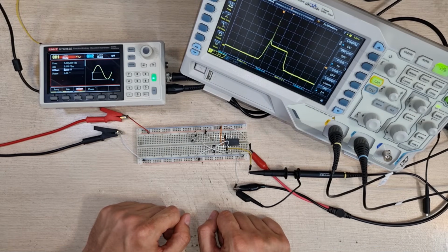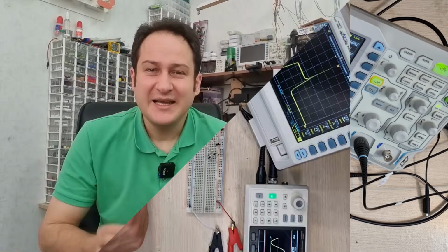If you refuse to use this diode here, the microcontroller in your circuit will reset every time the relay switches off. It is not just relays. All types of inductive loads make spikes, like DC motors, buzzers, solenoids, etc. And it is strongly recommended to use a flywheel diode beside them.